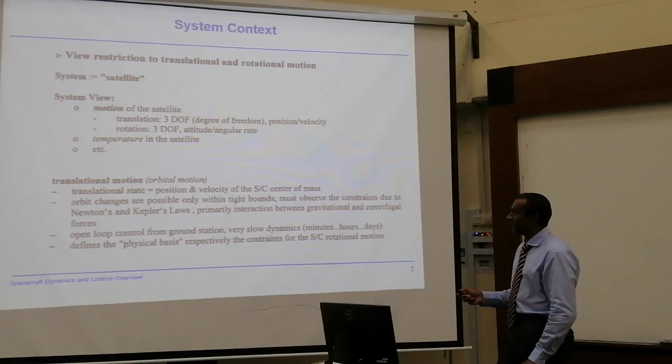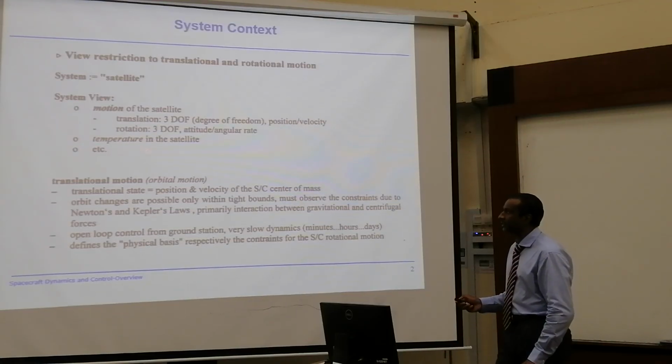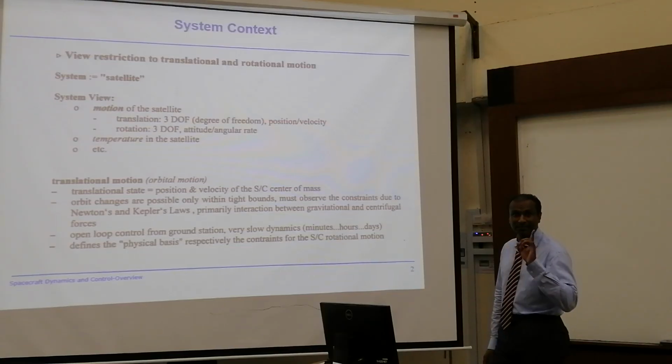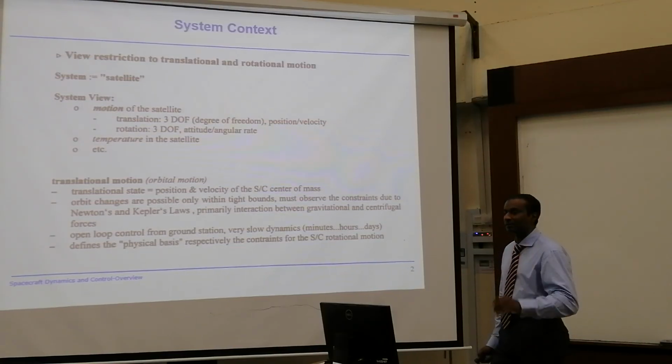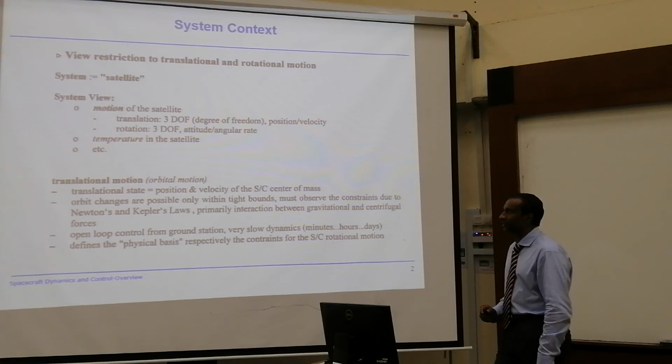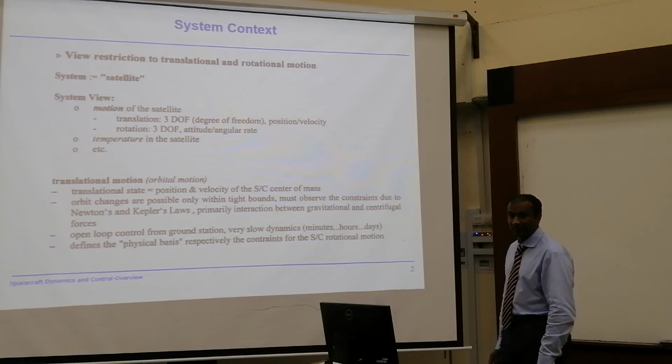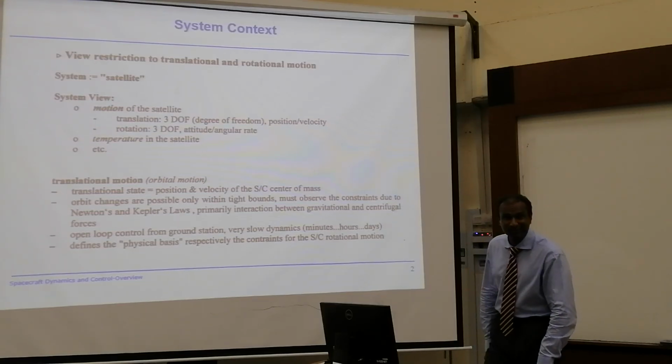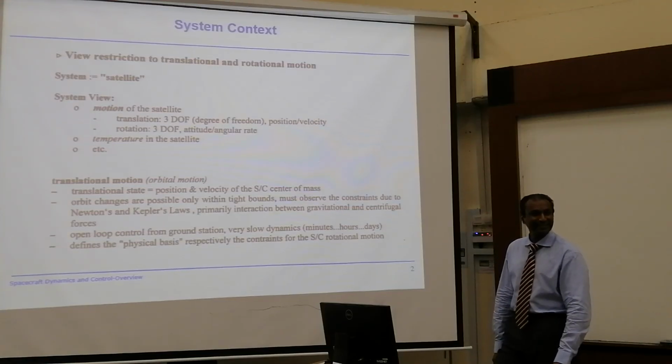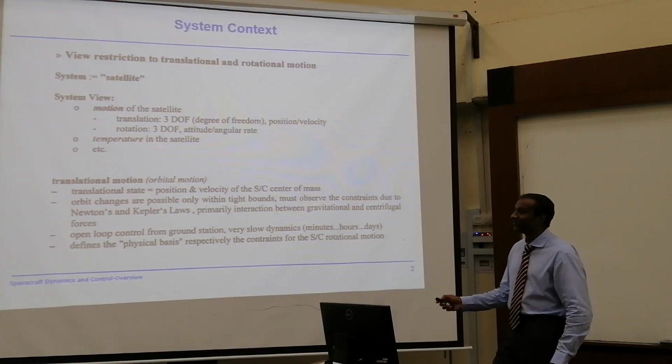Again, temperature of the satellite is, of course, important in the system. The reason being, performance of all those actuators, especially sensors, the measurement, is very sensitive to this. So if you learn satellite technology, the thermal control system is extremely important. Even as you know, a maximum temperature of 50-60 degrees is a lot already for a satellite. It is not too little, it's a lot already because of the sensors. Sensors are very, very sensitive.